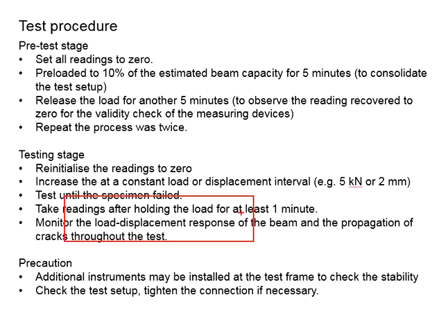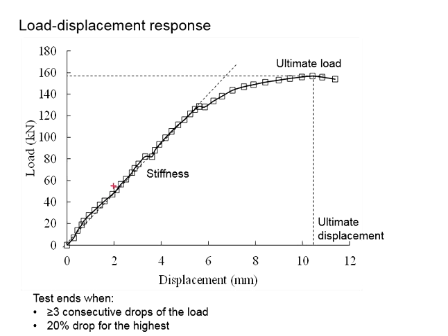Monitor the load displacement response in real time. This will help you to make a lot of important decisions throughout the testing. Knowing that the testing can only be done one time, you will need to monitor the load displacement response carefully. Throughout the testing, you will monitor the progression of the plots on the curve to ensure a smooth load displacement curve. Make sure the plots are more or less equally spaced throughout the entire curve.